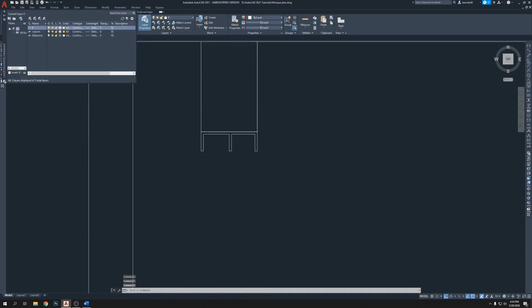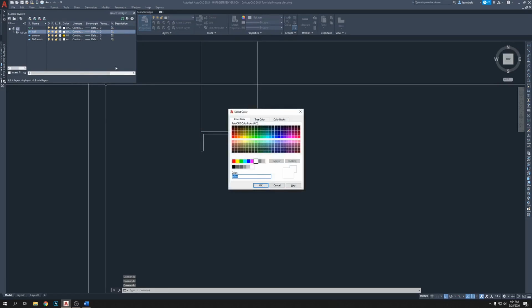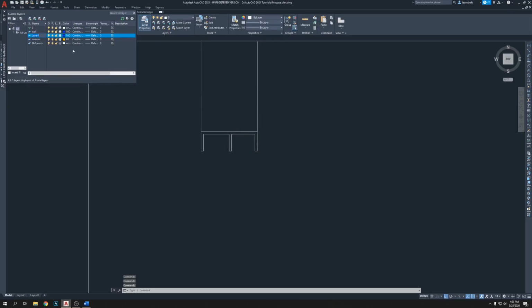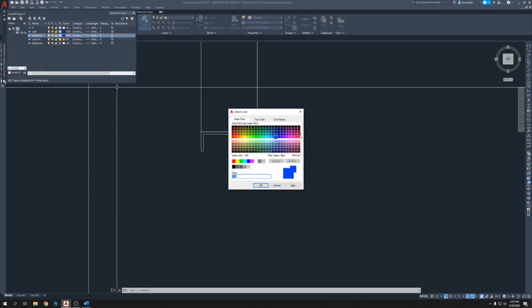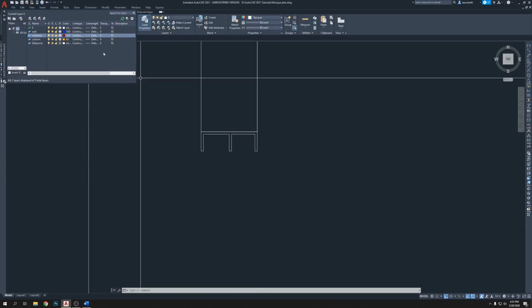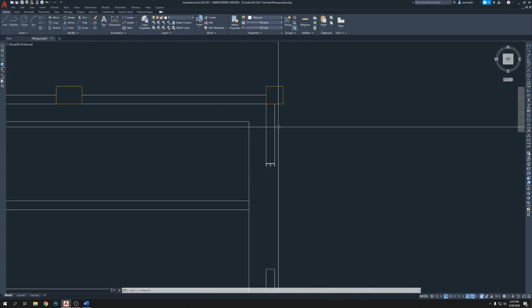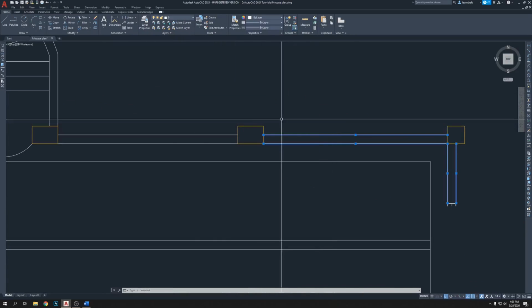So let's click on the layer, create a new layer, say wall, make it color like maybe light blue, okay, and then create another layer, make the name windows, make it color like a little reddish, okay, and close. So now these are walls, right? Wall, wall,